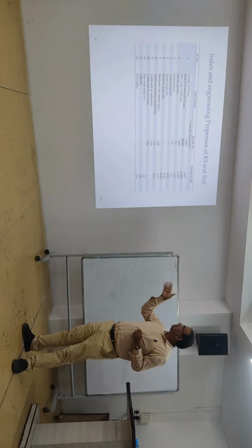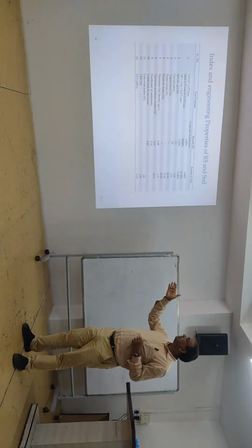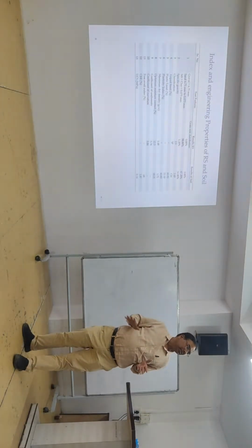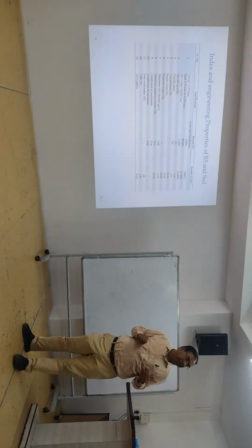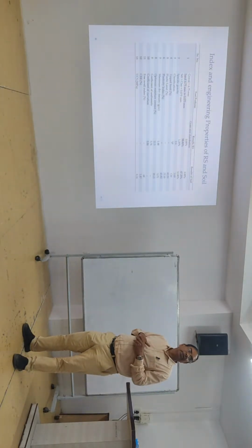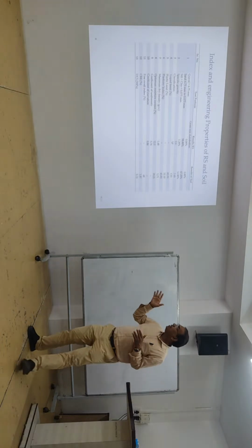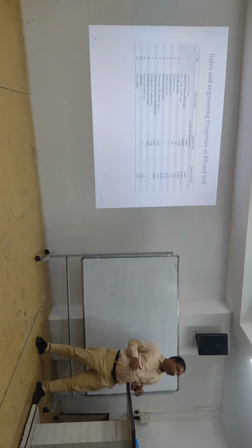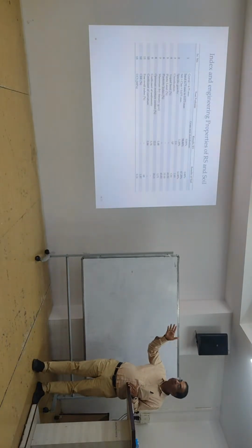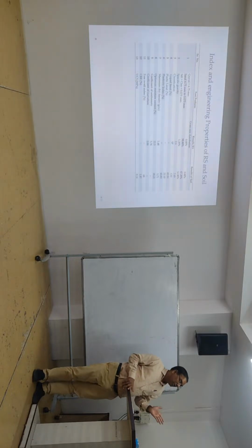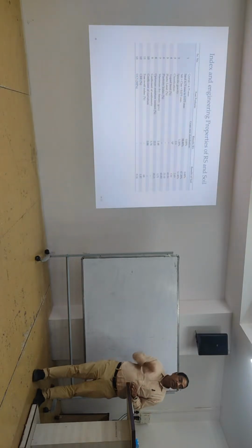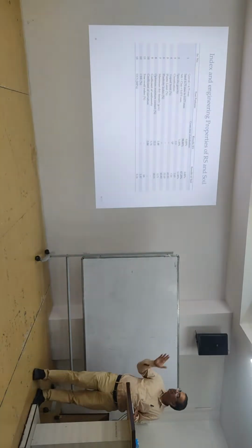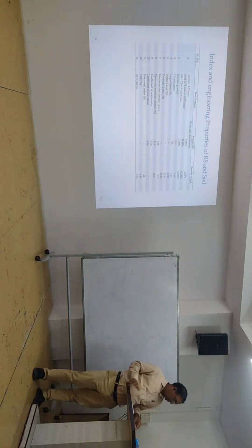So you can see that gradation is good, just like this non-plastic material that is required for the road construction. So this is the property that we get. That is mostly non-plastic, means there is no black cotton soil. This recycled sand is having. So this is almost as good as sand.